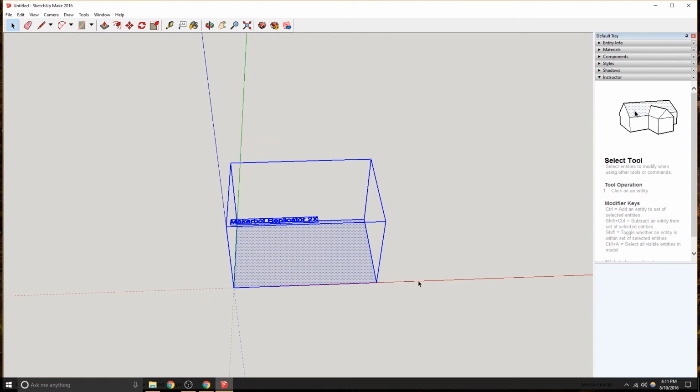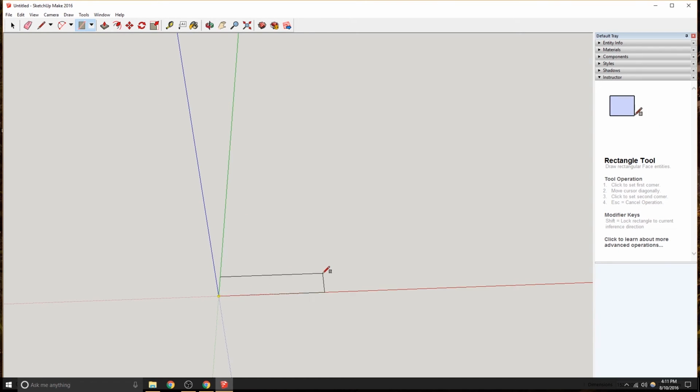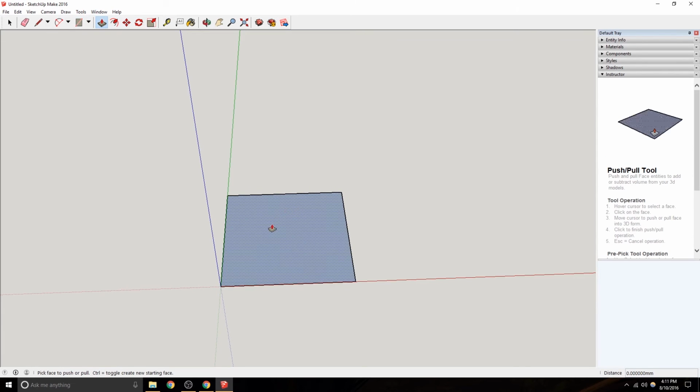Alright, moving on. So let's just pretend that you know how to do everything like that, or most of you probably already do anyways. Next thing we're going to do is create a line or a box. You can go up, create whatever size you want. We know that our printer bed has 200, 200, and you'll see it being typed in the bottom, hopefully. Hit enter. Yeah, it should be down here. Looks like it's slightly underneath the taskbar. There we go. Okay, 200 by 200. So I typed that in with a comma between. It created this.